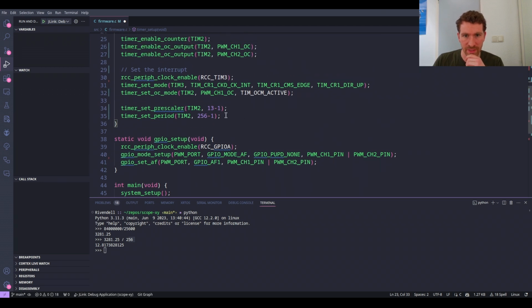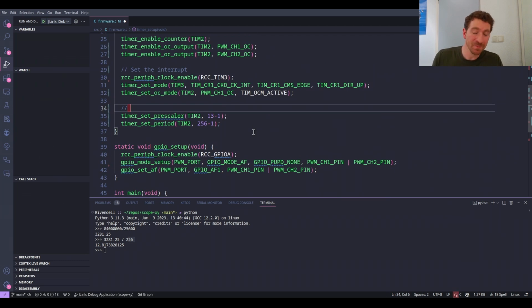So in order to do this, I'm just going to tell you that actually I want to run at about 750 Hertz. This is the amount of time that we will run, and how often we're going to change which point we're outputting on the duty cycle. Like which analog point are we showing at any given moment? And I want that to be about 750 times per second.